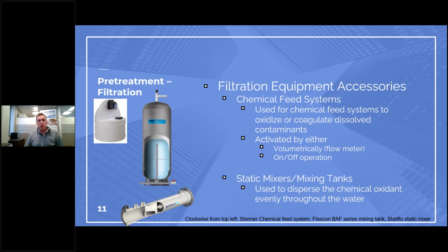And what's nice about the contact tanks is that they do provide you some contact time. So if you are dealing with a particularly stubborn contaminant, that gives you additional time there. Whereas the inline static mixers, generally speaking, are used for higher flows, and then you may need some storage thereafter.